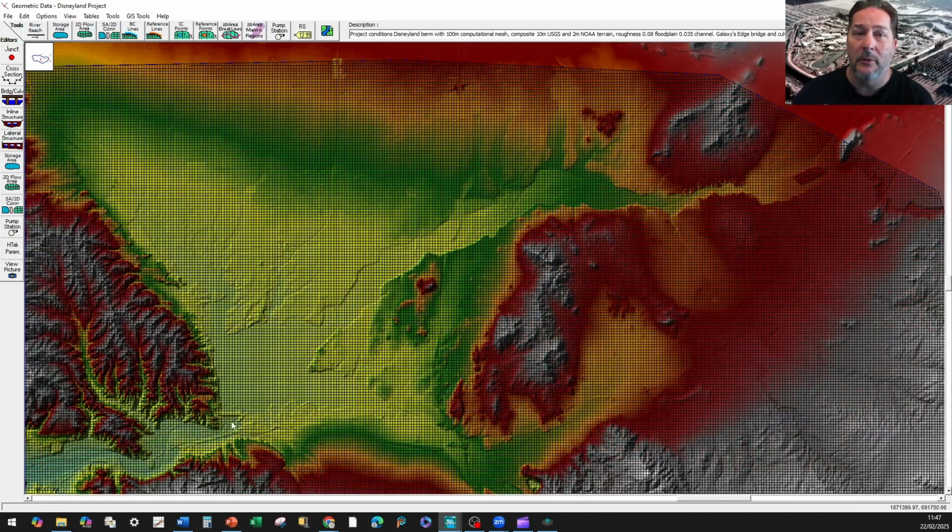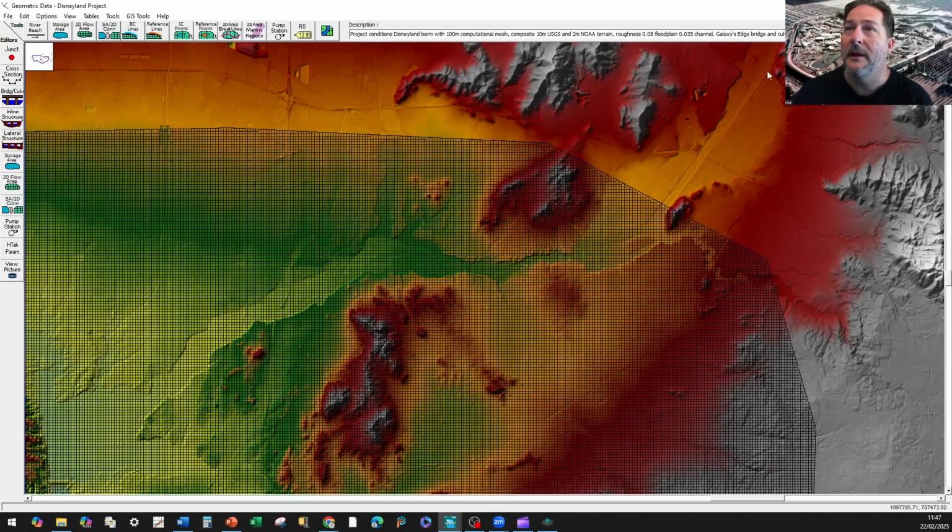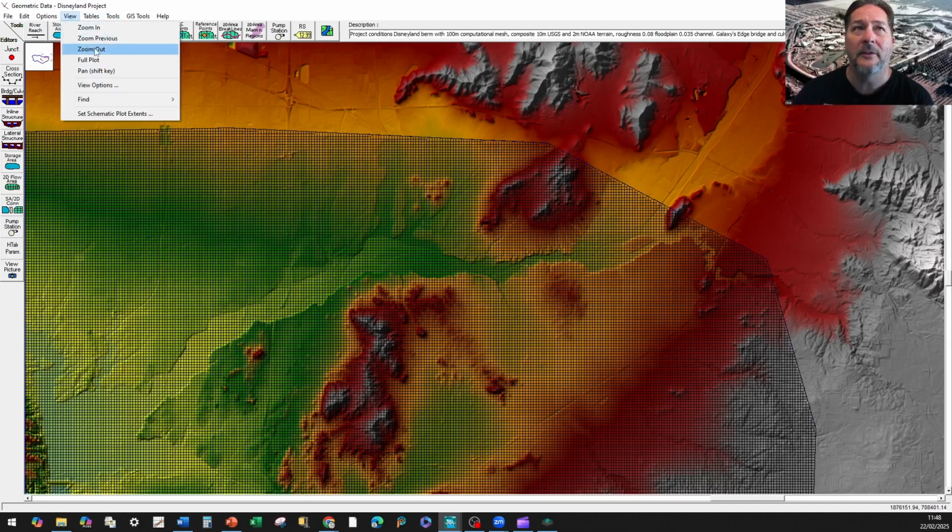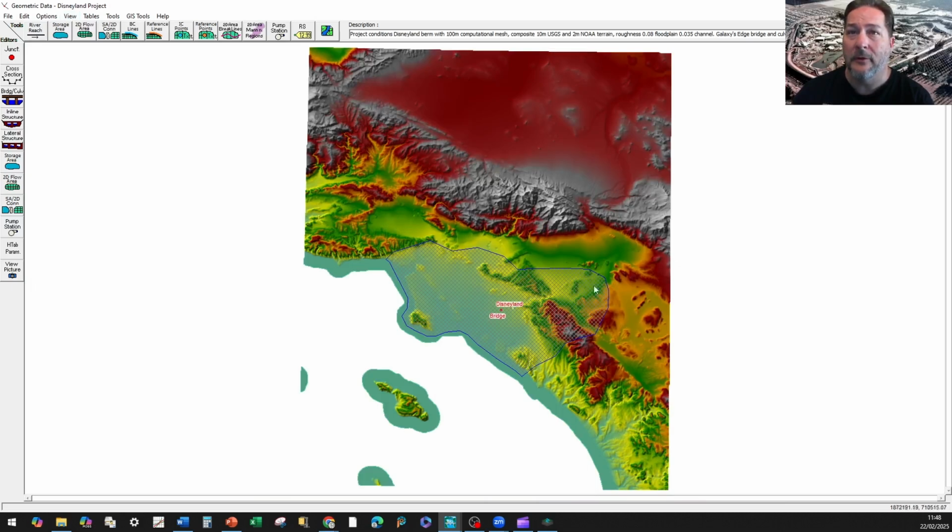And we'll go ahead and bring some internal inflow here, but to start with, let's grab an external inflow boundary condition that's going to represent what's coming in at this point here. Now, the orientations of the lines that we draw don't really matter for boundary conditions. So if I go out to the full plot, and if we picture this like a clock face looking down, it doesn't really matter whether you're delineating these in a clockwise fashion or anti-clockwise or counterclockwise fashion.